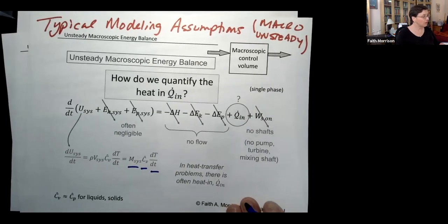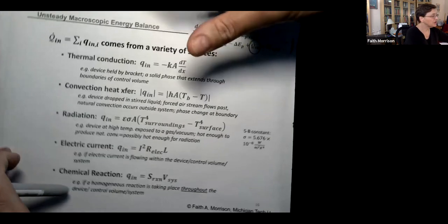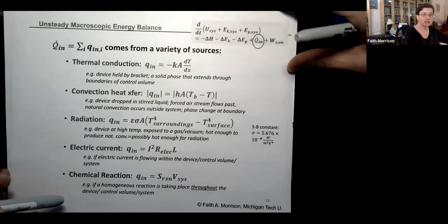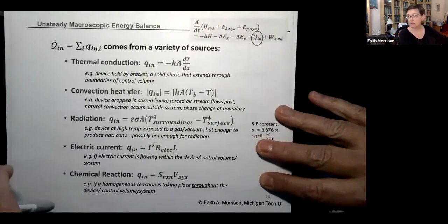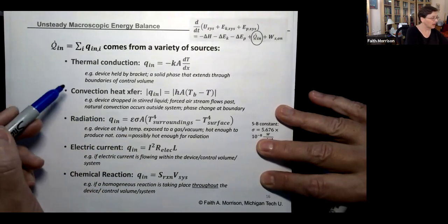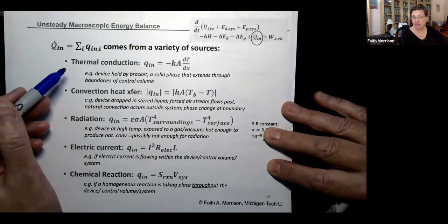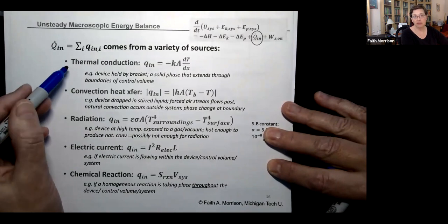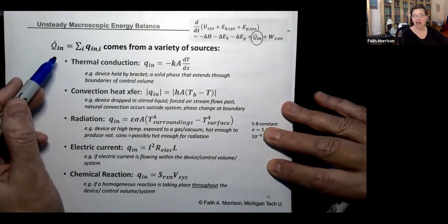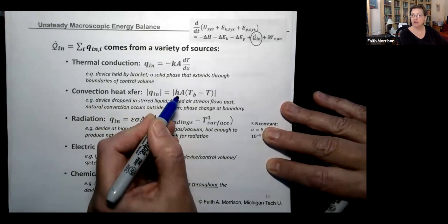And then the Q, going back to the lecture notes, I gave you a summary sheet of the various Qs, and we just have to go down the list and ask, is there something in thermal contact with the part? And by the way, the question about this is not about air or water or liquid, because the air and water and liquid are in the heat transfer coefficient.